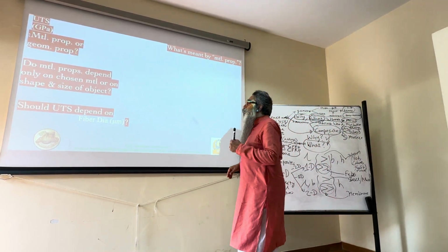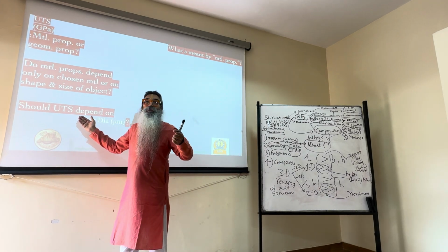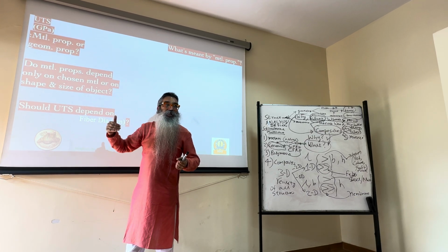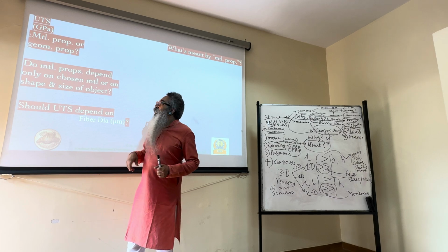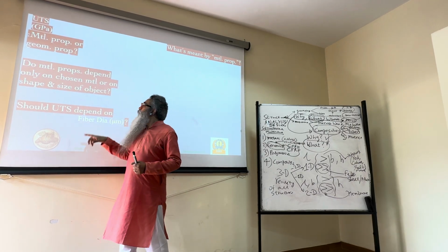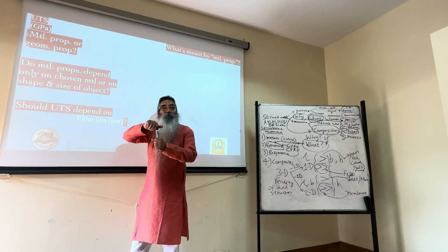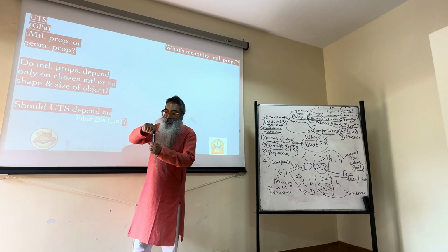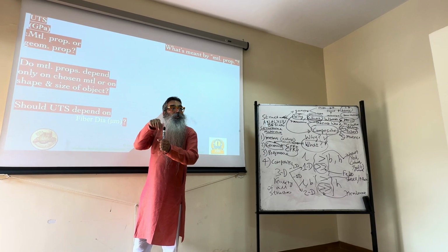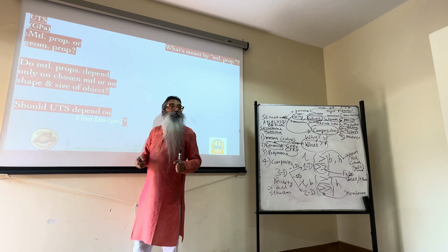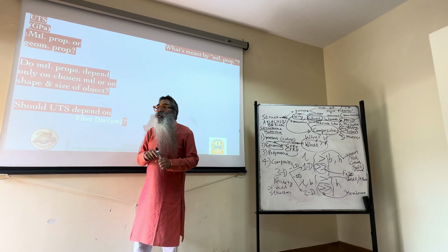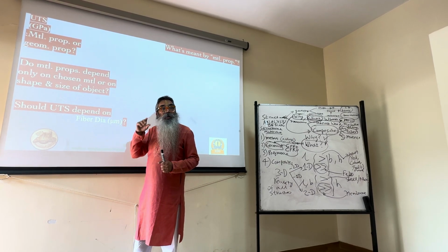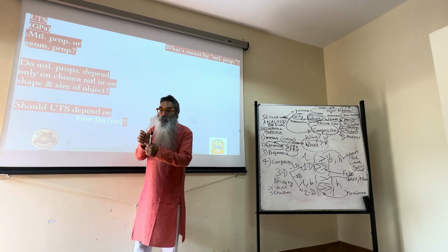So it's obvious because the UTS, as one of you mentioned already, is a stress, but a stress in a limiting sense. It's the maximum stress that a particular material can take in tension in a particular direction, which we call uniaxial, the axial direction. And so that particular failure should be a material property. But if it's a load, then that load gets distributed over the cross-sectional area, and if I change the diameter, the cross-sectional area changes. Therefore the stress at which it fails might be constant, but the actual load at which it fails will depend on the area.